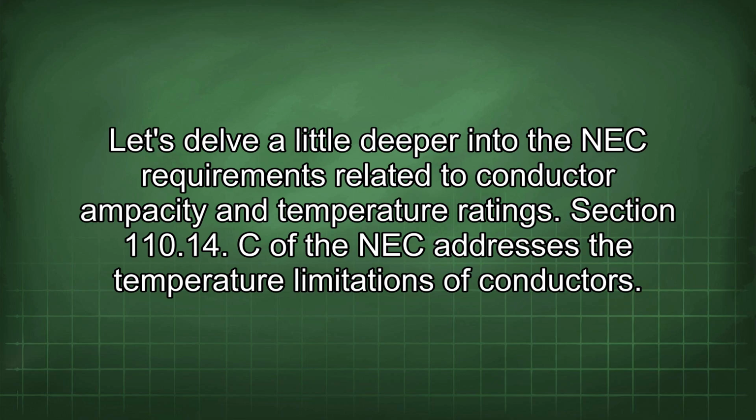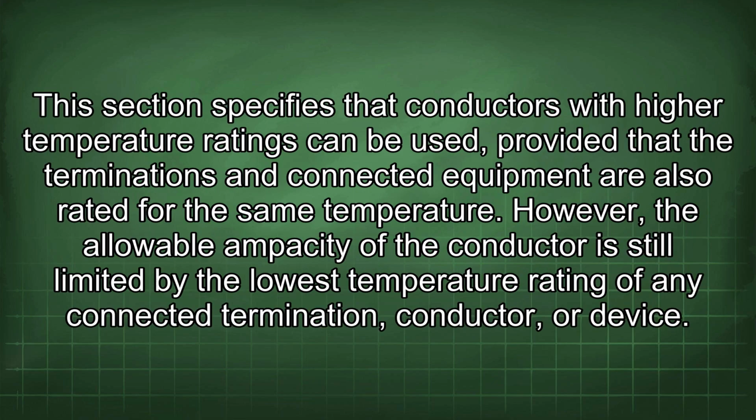Section 110.14(C) of the NEC addresses the temperature limitations of conductors. This section specifies that conductors with higher temperature ratings can be used, provided that the terminations and connected equipment are also rated for the same temperature.